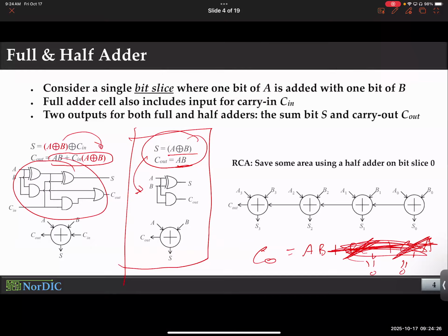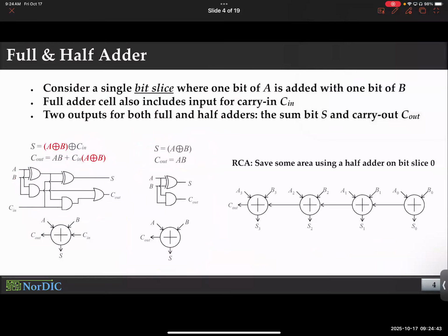So if you're wondering, okay, what's the big deal? I'll use a full adder and make the carry 0. Instead of doing so, if you create something called a half adder, this is often mentioned as a half adder, that significantly reduces the area. And that's a big deal. And it is even a bigger deal. You haven't seen that here. It's not part of the syllabus, but I teach it in 433, for example. There is a lecture on multiplier, adders and multiplier.